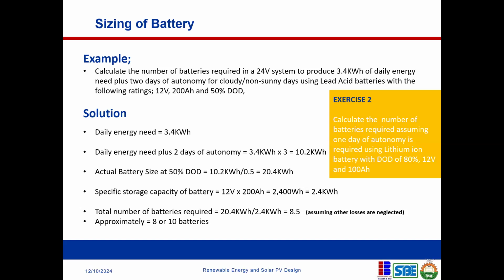I'm sure most of us have seen battery installations where you have to put an air conditioning system to maintain the temperature, whereas in some cases you see battery installations that are exposed to high temperatures without any temperature control. In that case, you expect more losses compared to a battery installation with controlled temperature. So they're not cast on a rock, but give or take, if you have taken measures to limit these losses, you should expect about 5% charge and discharge losses. That's why in some cases I put them as negligible, because it depends on the prevailing conditions of your installations.